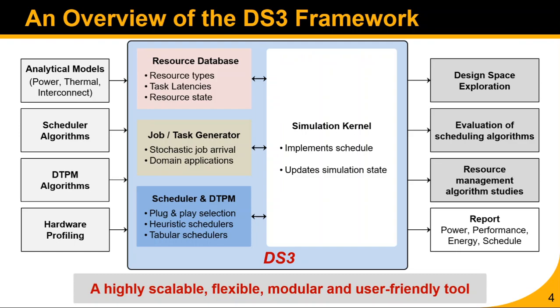The framework aids the design space exploration of DTPM techniques by utilizing these power models and commercially used dynamic voltage and frequency scaling (DVFS) policies. DS3 also provides plots and reports of schedule, performance, throughput and energy consumption to help analyze the performance of various algorithms.